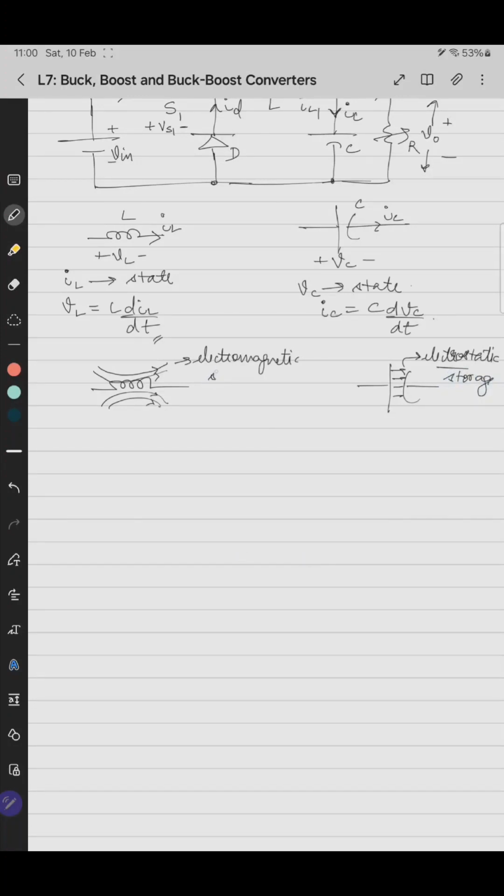If we see how an inductor and capacitor behave, if you excite an inductor by a voltage supply, then some voltage is applied across the inductor, and thus a current will try to flow through it. Based on the load requirement and any change in the circuit, the current of the circuit will change, and an inductor will not allow sudden change in its current. So it will have some lag before the change in the current.